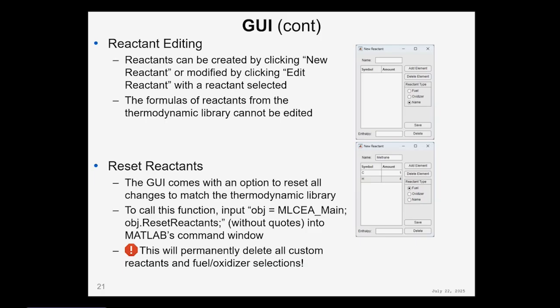After that, you can completely define your own reactants within the problem call by saying, here's the name of the reactant, here's the formula, and the enthalpy and the temperature that I'd like to use. And that will always work within it. That also allows you to just loop your problem and adjust enthalpies or temperatures for your propellants within your models.